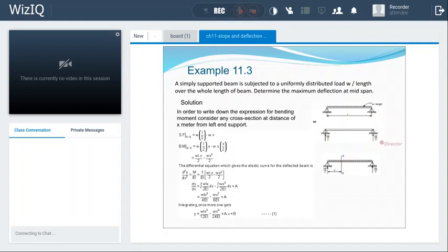Here we have these two reactions, and then you can see here this equation for bending moment at a section X we have to write. This is X here. So at section X we have this value WL by 2 into X. Now there are two forces. You have to be very careful when you are writing the equation now. This force is acting upward.